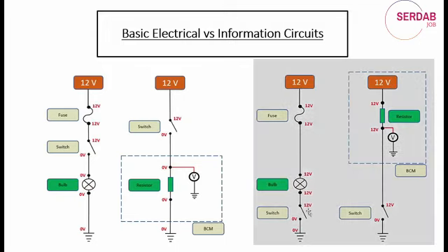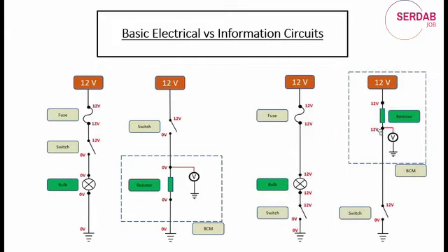And the only difference is on the ground side switch, now let's come over here to this side. On the ground side switch, I have 12 volts past the load, just like I do over here. I have 12 volts past the load, and then when the switch closes, this reading up here is going to change. That reading right after the load is going to change. So let's watch that. Notice how that changes from 12 to 0 right after the load.